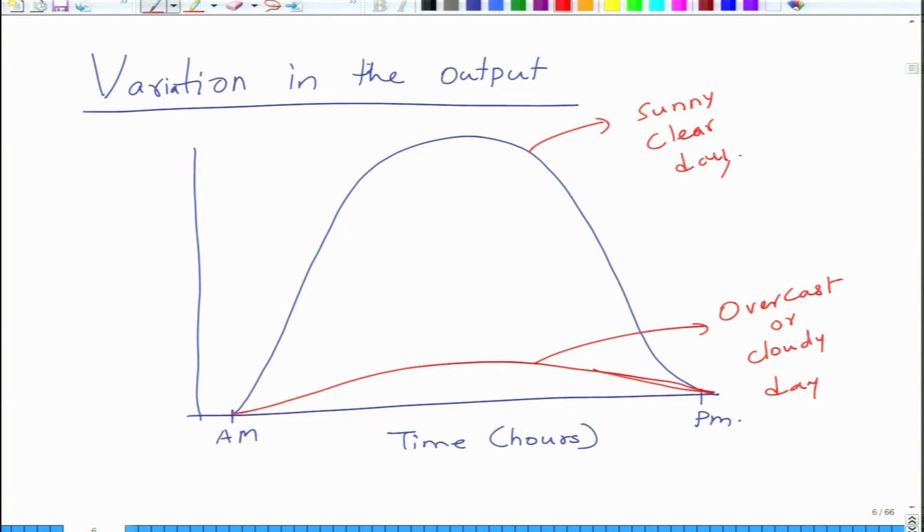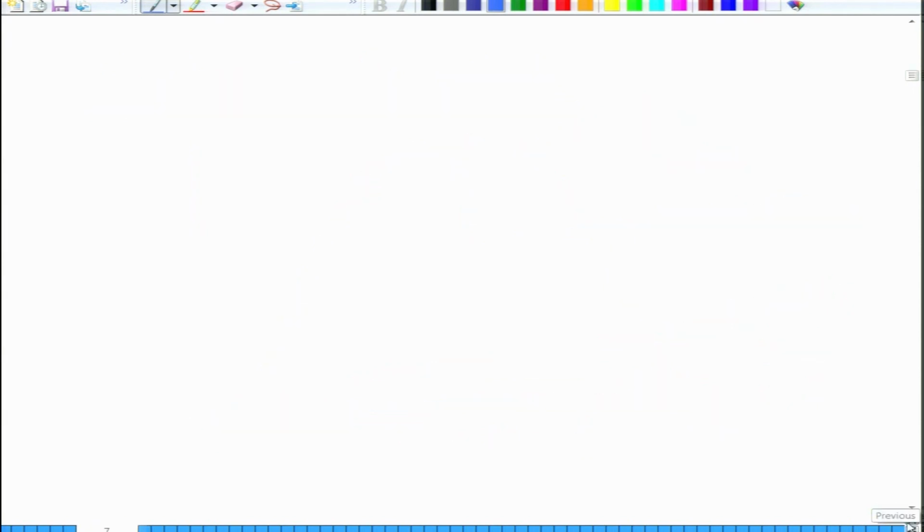So, there is a huge difference, and this is for a given tilt angle and so on and so forth. This is for a solar surface, the amount of energy that is incident, which is going to determine the output current, let us say, from a solar panel. There is a huge difference in the output, so this is substantial. How much output your solar cell is going to produce depends upon the sky condition or the cloud condition on that particular day.